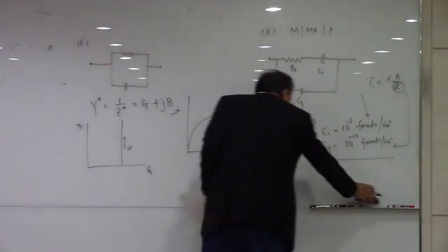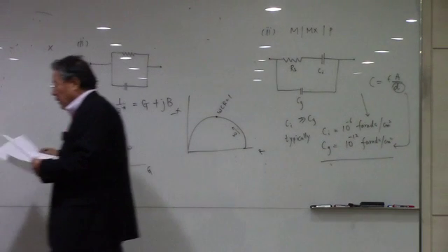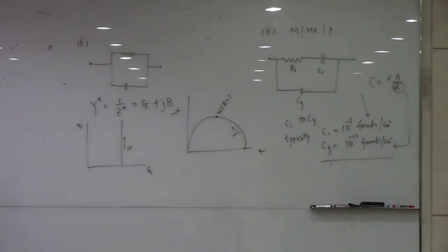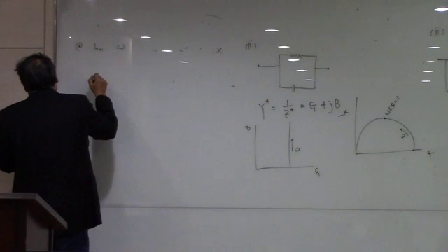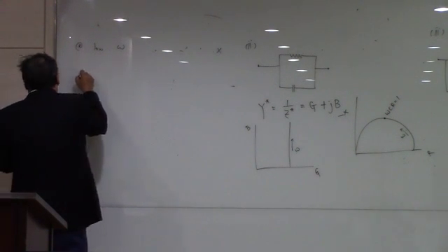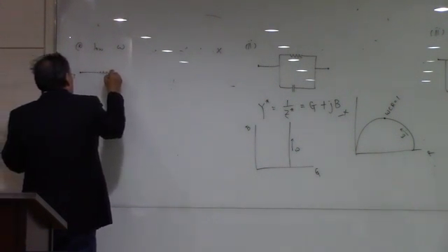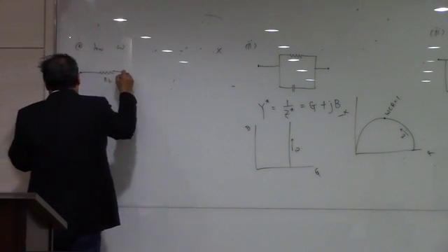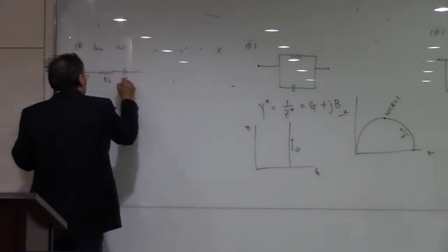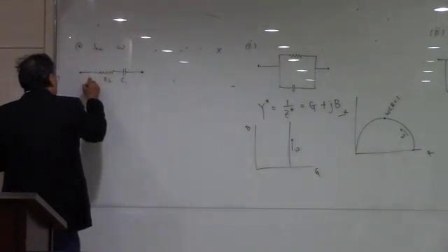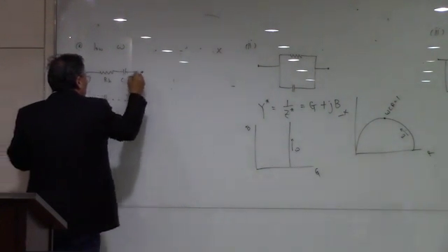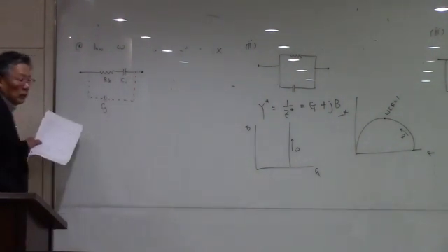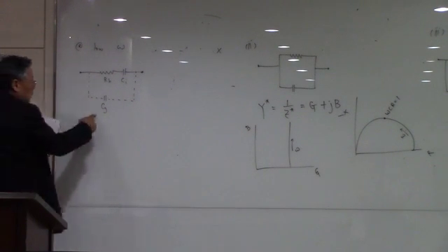So just intuitively we can see that at low frequencies, okay, the circuit now has Rb and Ci here, and this Cg. We are not going to have any current through the Cg.